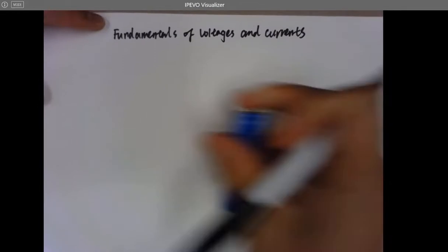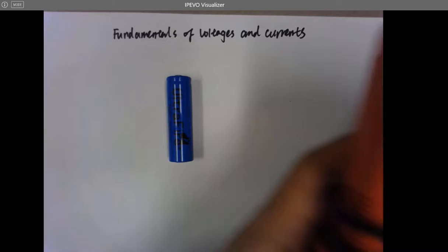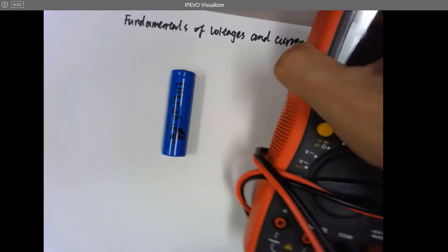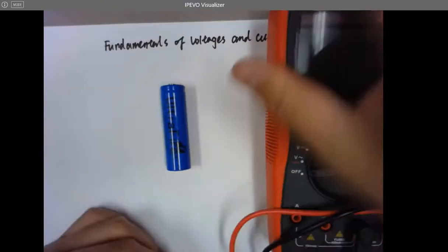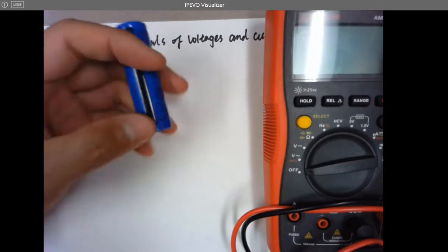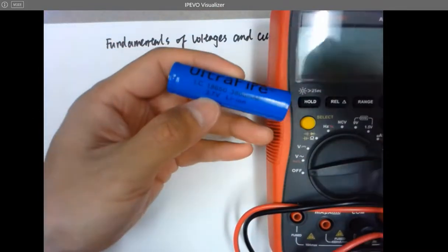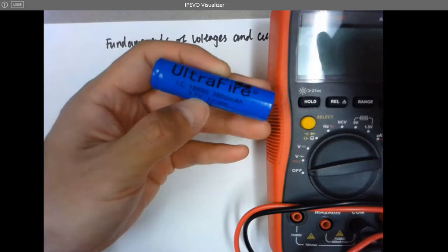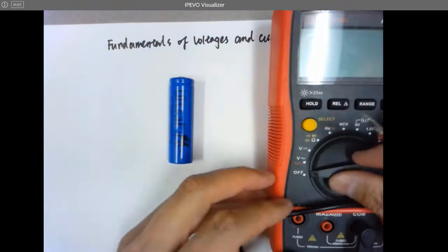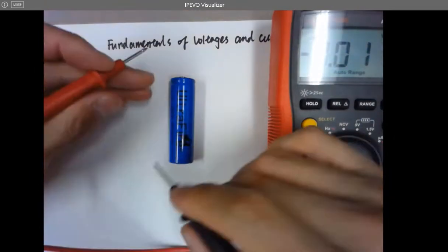So for example, right, so this is a battery. You have seen this before in the past or everywhere in real life. And this is equipment. It's called multimeter. And so this one can test or can measure what is the voltage between these two terminals. So you know this is the positive terminal, this is the negative terminal. And if you see the readings, the voltage reading here is actually 3.7 volts. And I'm supposed to get 3.7 volts if this is fully charged, but I'm just trying to show you how to measure the voltage between these two terminals of the battery. So let's take a look.